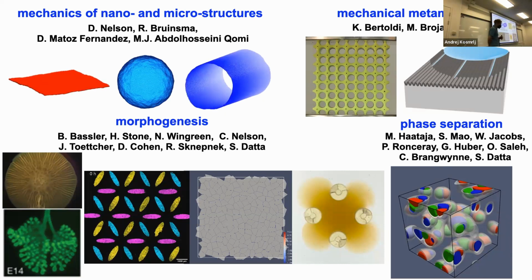In the last few years, we also extended some of these results to try to understand what is the role of curvature. For example, if you have spherical shells or nanotubes. Interestingly, because the mechanics of the shells is very different from the mechanics of flat plates, we found that thermal fluctuations in spherical shells generate an effective compressive stress, which is entropic in nature. If you crank up the temperature high enough, this compressive stress becomes so large that the shells become unstable, even in the absence of any external load, such as pressure, right? So they'll just become unstable on their own.